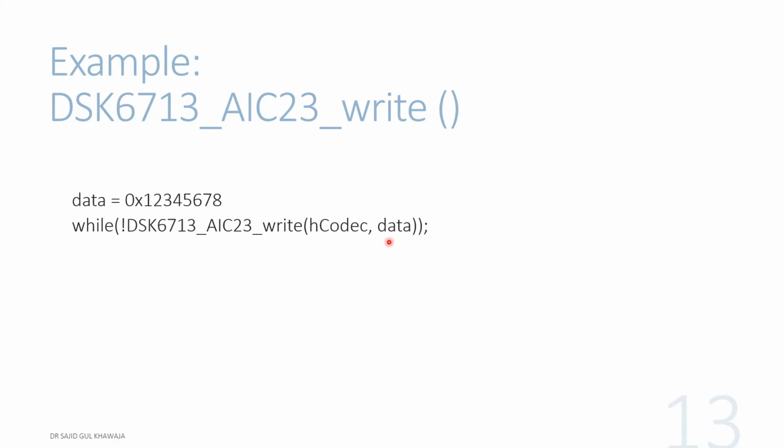If you look at this terminating condition, it's telling this while loop that until the write command returns 1, we will be stuck at the while command. It means that this while loop will keep on working until a successive write has taken place. So essentially it creates a loop until the port is ready to transmit the data. So this syntax essentially can be used for read as well. Both these syntaxes will be stalling the system at their particular location until a relevant read or a relevant write takes place.